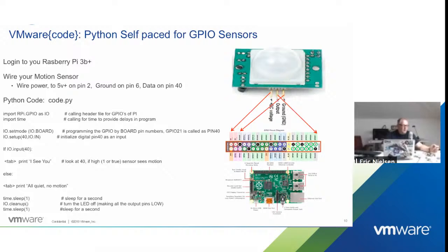We realized after a while that this little yellow data line was acting as an antenna, and there's so many waves from Wi-Fi hubs that there was so much energy that it was driving the voltage up on that line past the 0.5 volts, and it was sending a high, and I was reading a high voltage. Even though there was no sensor data, I could actually unplug it and then read the voltage on the line, and it was coming high because we had so much electromagnetic interference in the room that it acted as an antenna and was pulling that voltage right out of the room.